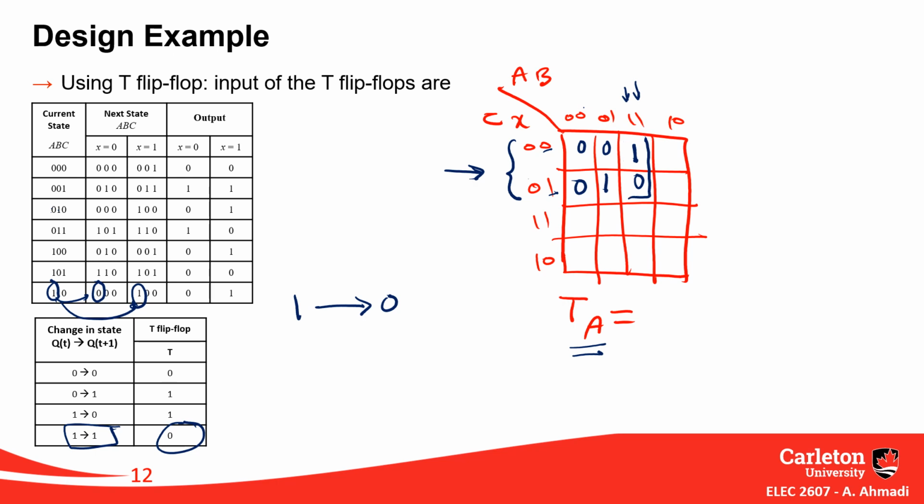So we have to repeat that for every single transition, for each state in our circuit. So how many do I have? For A, I have this, which will be transformed to this, and this, for X equal to 0 and X equal to 1. All the rows, these two are don't cares, we don't have those combinations. The rest of them, one by one, need to be examined. One by one, you have to check.